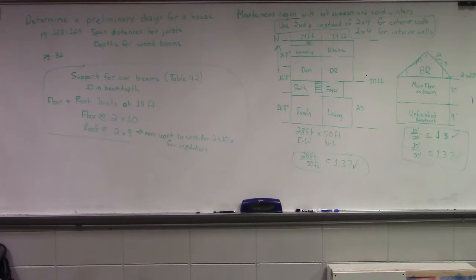What we do is that every 20 feet, we've got to have a shear wall, but it's got to have a panel. If the wall is so long, it has to have a panel, and if it's over 20 feet, you've got to have a second panel. That might be a code requirement. It is, some sort of, I mean, that's the best practice, engineered to pacify the state code. Sure, sure. I'm just getting confused.